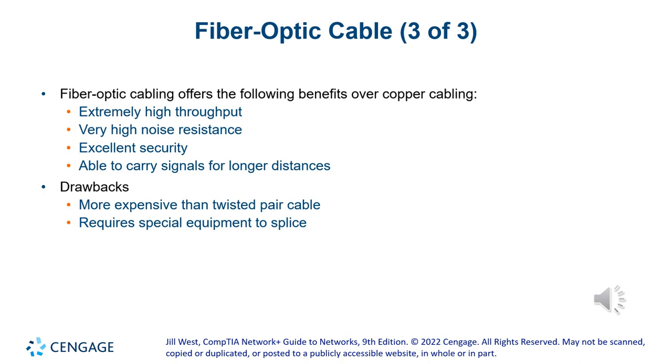attenuation of the signal. You lose some light, but not as much as electrical signal when you go on a copper wire. The copper wire has more attenuation. We talked about that term before. Attenuation, when you lose signal. A wire will have more attenuation than a fiber. With fiber, you still have some attenuation, like I said, because when you bend, some of the light tries to escape.